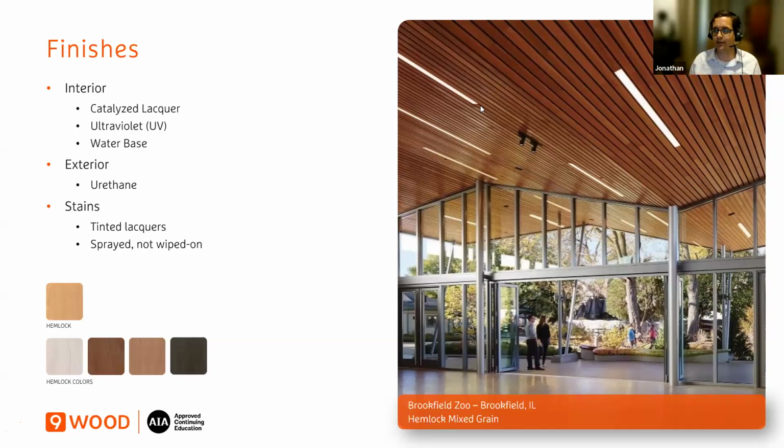Common in flooring, it's more durable, but it's thicker. It kind of hides the wood a little bit more, with more of a plasticky look, not as necessary in a ceiling. And then water-based. One thing to keep aware of in water-based for interior situations is there are currently some compatibility issues between the fire rating applied to the solid wood, whether soft or hardwood, and the water-based treatments. Manufacturers are working on dialing in that technology, but that can be an issue. It's why a catalyzed lacquer is very common as a choice.